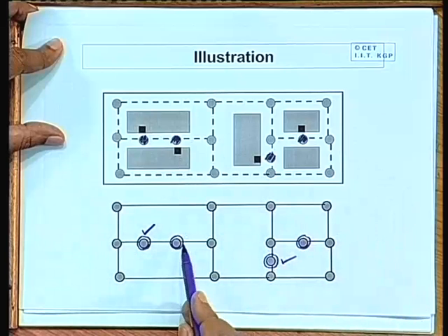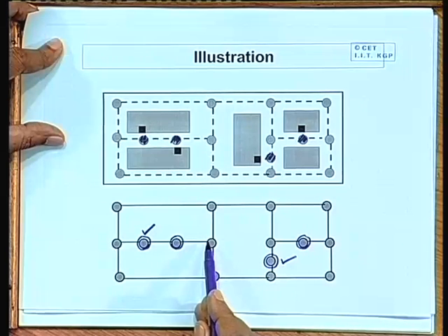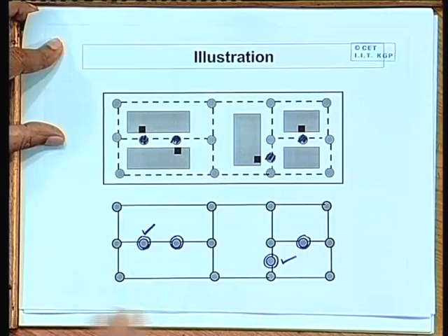As I said, each edge will represent the channel capacity, and that also has to be taken care of by the router. So, as nets are routed, the channel capacity will be going on decreasing. At one point of time we are just connecting 2 points. These methods all connect 2 points at a time. So every time, after connecting 2 points,